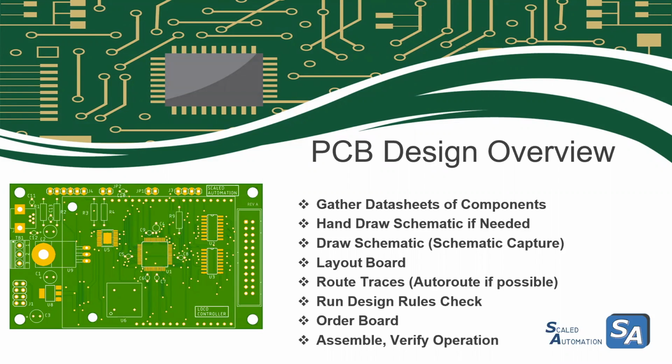Once the board has all the parts placed in the correct locations, then we can route traces, and Eagle has an auto router. I find it difficult to use, and it usually doesn't route the kind of stuff I'm doing because I'm trying to make the boards as small as possible. I will almost always route all my traces by hand. And then last step, once you got everything done, you think you're all done, you're not, because you're going to run a design rules check. And design rules looks for things like proper spaces and hole sizes, distances from boards, component distances from each other.